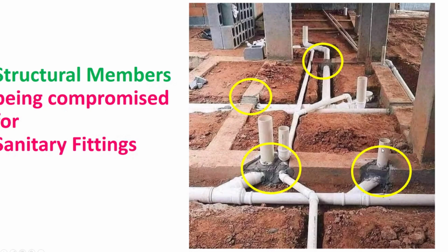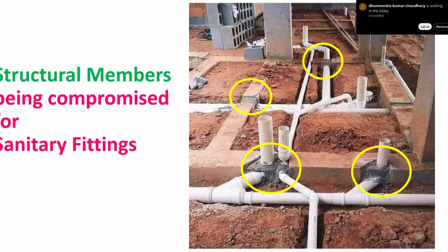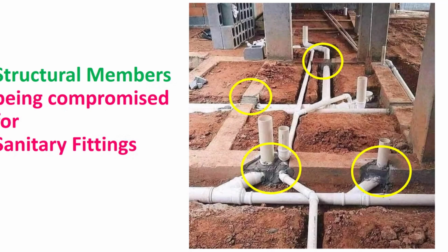This clause is very important: in case during construction the soil or the rock for which the foundation is designed is not found to be in the condition assumed, the foundation should be redesigned. Okay? So again, this is suitably altered. So I need to have the bearing pressure suitably altered. Clear about it?